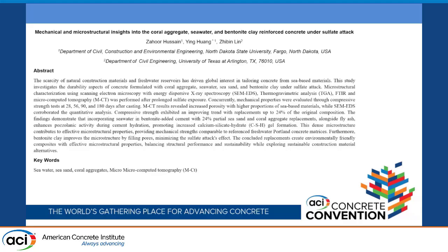In this research project, we used bentonite clay as partial replacement of cement, along with some sea-based materials such as sea sand and seawater, and we used coral aggregate as a replacement of natural coarse aggregates. We used sea sand and seawater as partial replacement of natural water and natural fine aggregates.